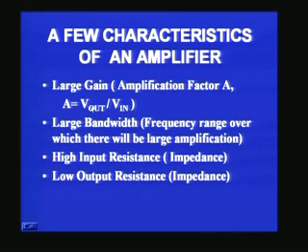So depending upon the configuration, the type of transistor or amplifier, the amplification factor can be voltage or current or power, and it does not have a unit because it is a ratio of either voltages or currents and things like that. So it is a mere number. Usually it should be very large if you want good amplification.